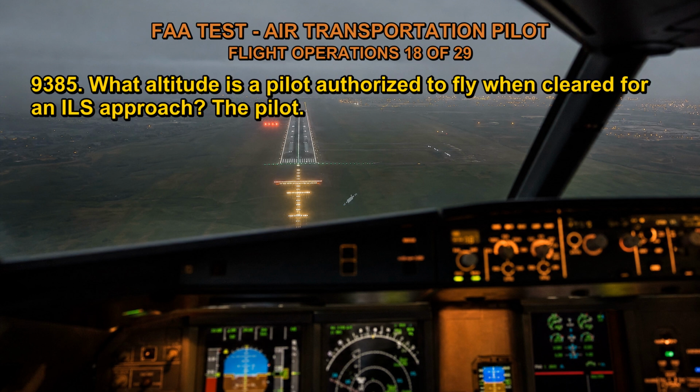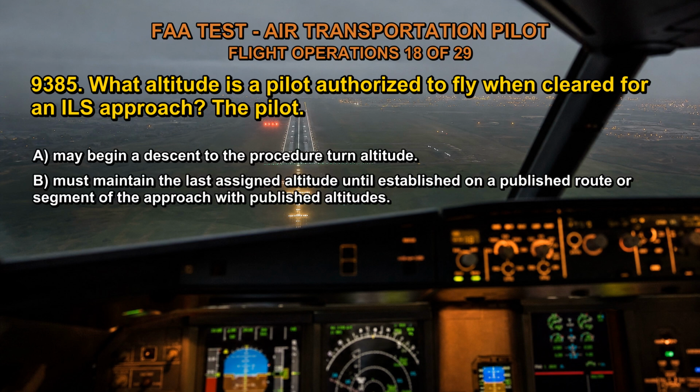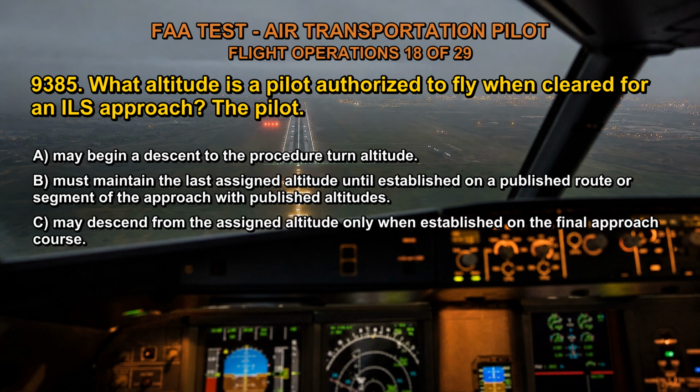Q9385. What altitude is a pilot authorized to fly when cleared for an ILS approach? The pilot A. May begin a descent to the procedure turn altitude. B. Must maintain the last assigned altitude until established on a published route or segment of the approach with published altitudes. C. May descend from the assigned altitude only when established on the final approach course.